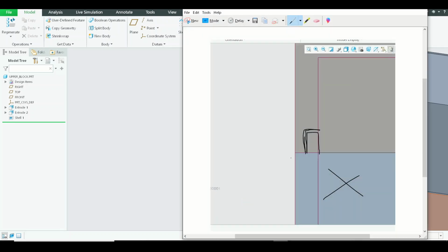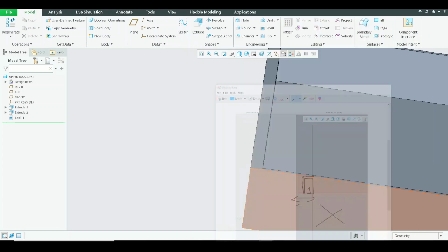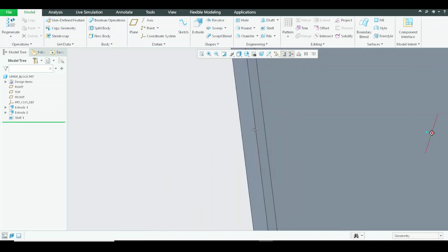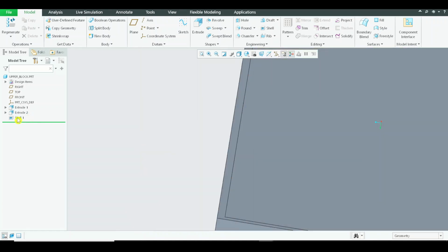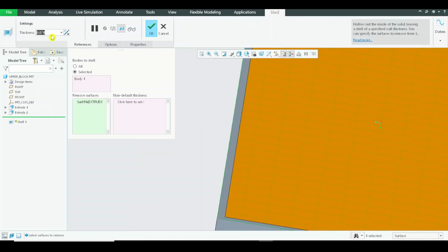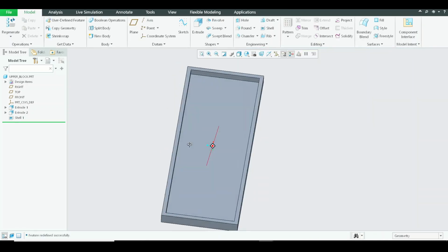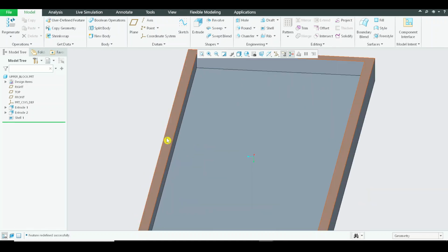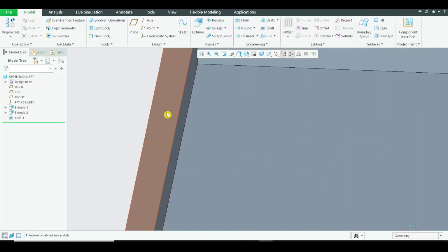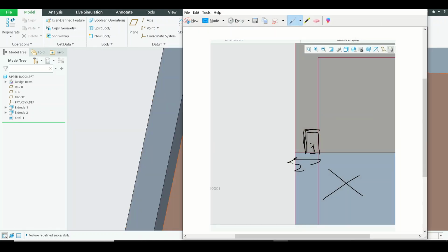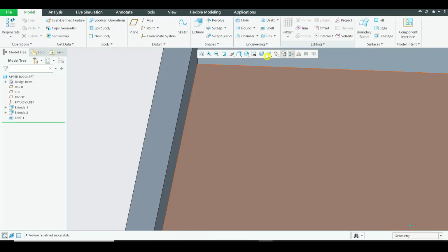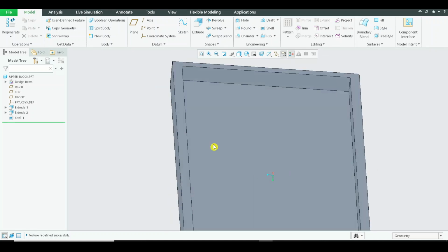If the width of this one is 2 mm, then this will be 1 mm, because this is looking like exactly half. What we can do to avoid this is increase the thickness of the walls. Let us make it double, so that it is 4 mm, 0.15. After making it 0.15, we will be adding another material on the top, so that will be 2 mm. So this is 4 right now, and this will be 2 millimeters. That will be easy for us to manufacture the part.